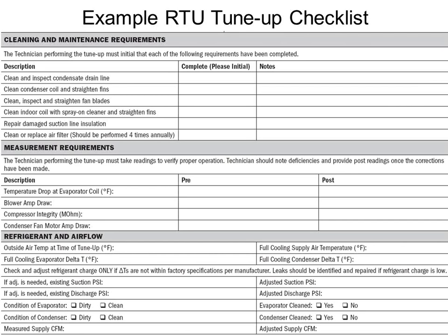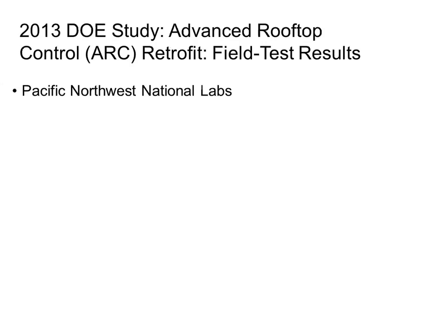Sometimes they need to put gauges on the refrigerant circuit if the temperatures are out of line. Sometimes you don't. If all the temperatures are in order, you don't really need to tap into the refrigeration circuit. So it just kind of depends on that. This is a typical chart, and there's a bunch of them out there like that. This is just one that I grabbed to show you. So getting things working the way they're supposed to work is step one. What we're going to talk about beyond that is, well, assuming they're all working correctly, what else can I do to save energy?